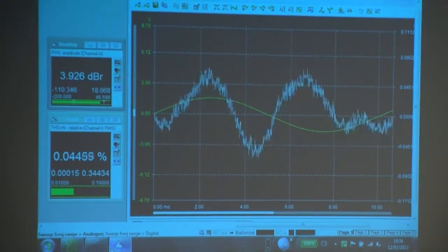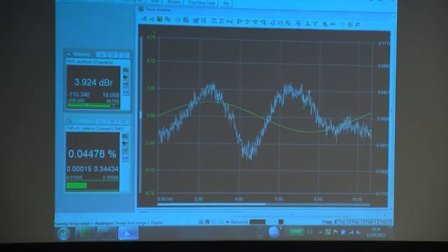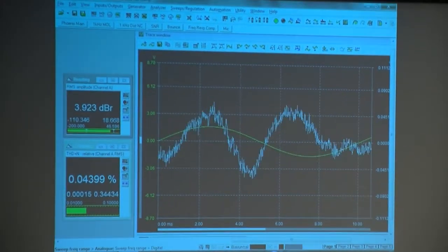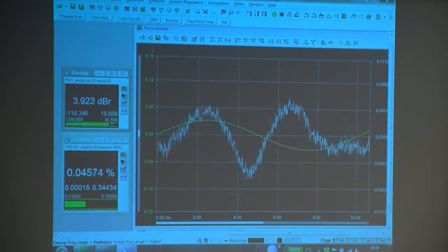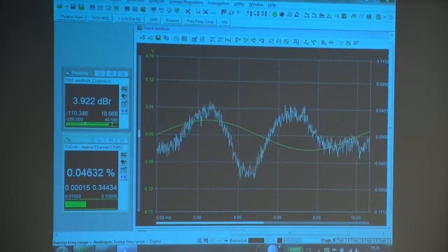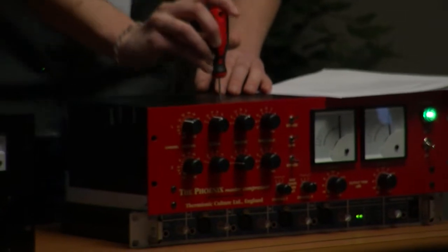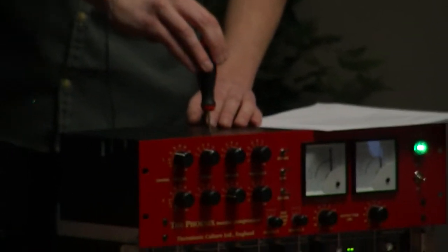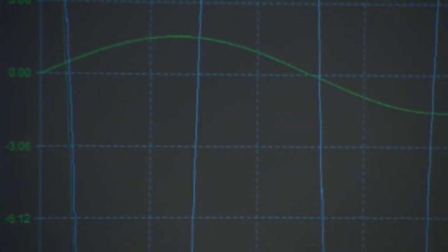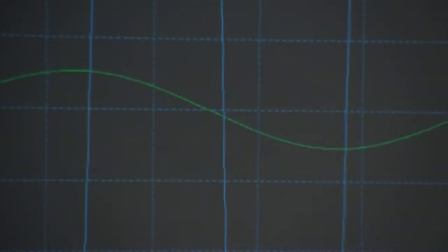During the test procedure, we have a potentiometer in the cathodes of the output stage of the Phoenix. And this is a really useful and accurate way for us to set up the unit for the lowest distortion. So I'll just quickly change it. So you can see here that all the way around we're not amplifying very well at all, 0.7, 1%.